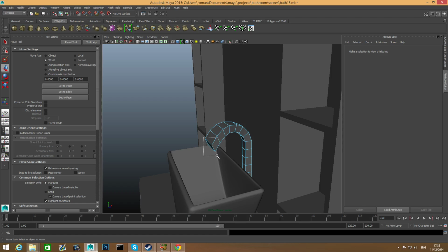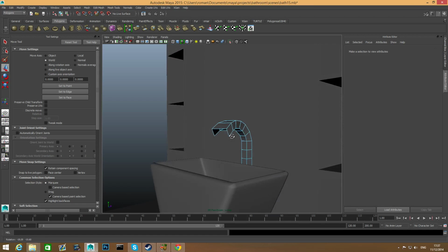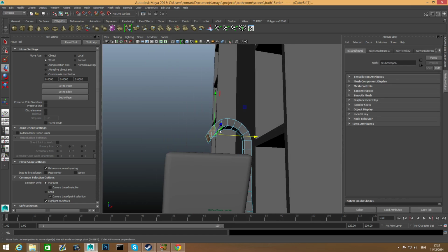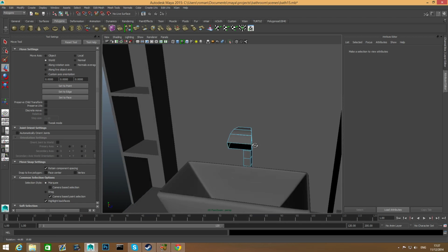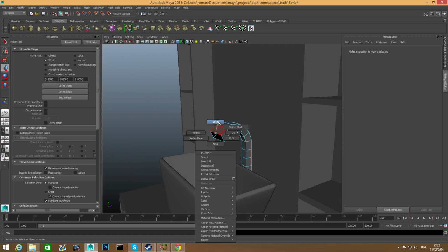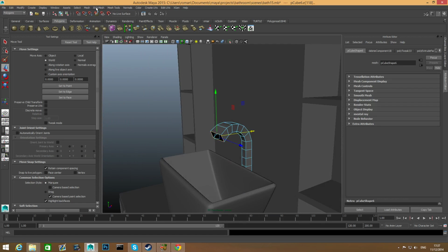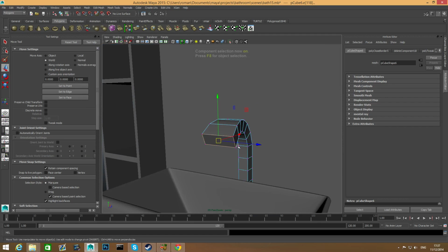I'm going to grab those 4 faces and delete them. Sorry, 5. Sorry, I just removed some face that I didn't want to remove. I'm going to shorten this and simply right-click, double-click on this edge, edit mesh, fill hole, and press F8.